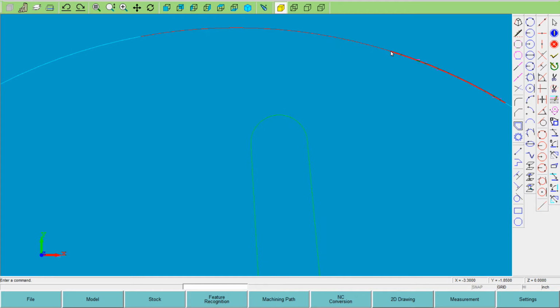Right? So remember, over in this area here is where the end line is. And remember, over here is where it is. You may have to put your finger or something on the screen to remind yourself so you can find it. This is a little bit tricky. We're going to turn on match line, this top choice here, match line. Now we get these yellow markers. Ignore the yellow markers. We're looking for the red dot.